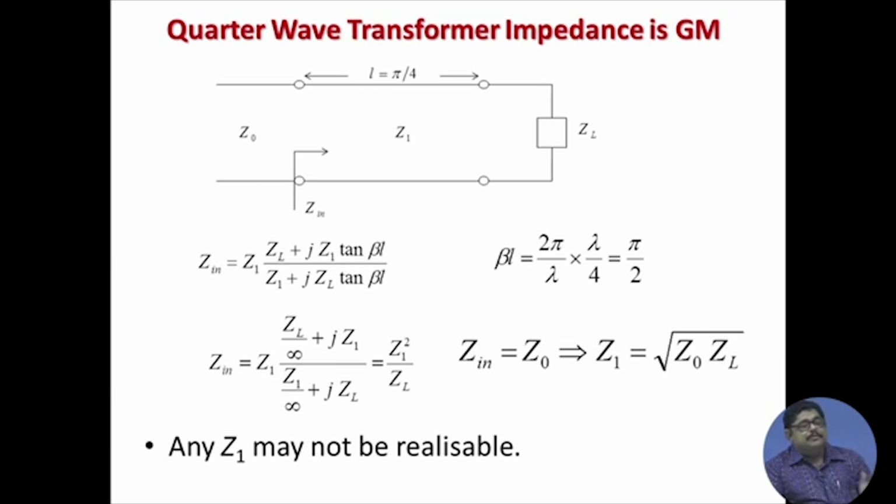So, at the design frequency this match gives a good impedance match, so reflection coefficient is 0. But the problem is that if we are a bit off from that design frequency, the reflection coefficient is no more 0. So, there will be a frequency response, and if we plot it, it will be quite narrow band and quite sharp.